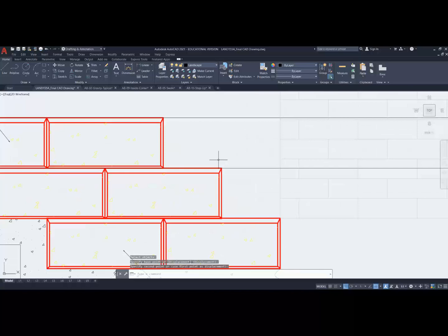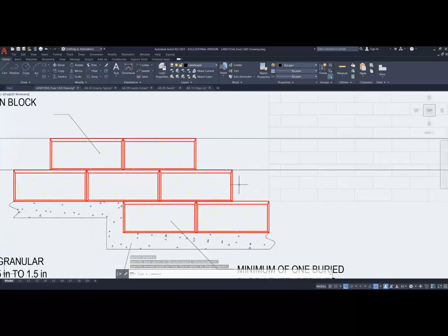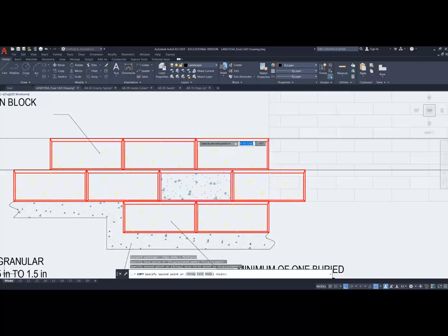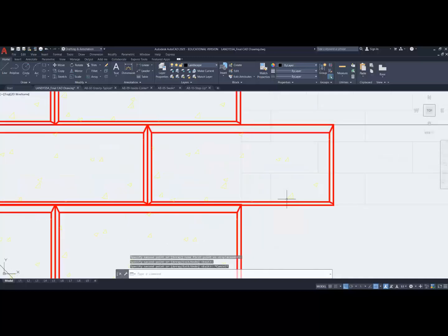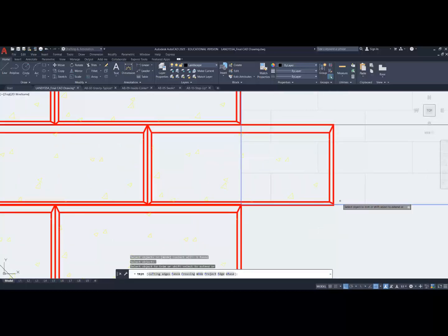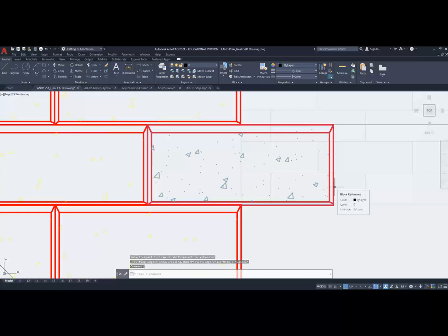And that's going to line up with the corner of the wall here. There's my brickwork. So all of the bricks that are here are either going to be full size as this or cut. So now I can copy some of this. That one's full size. This one's going to be cut. So trim to my line. Notice it's saying I cannot trim this object. Why? Okay, they've created certain elements with this.